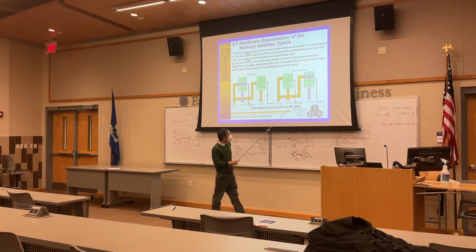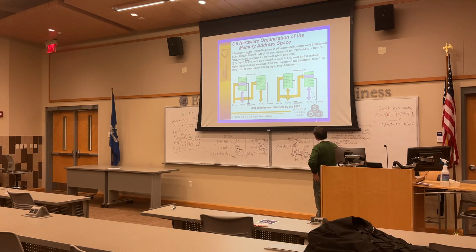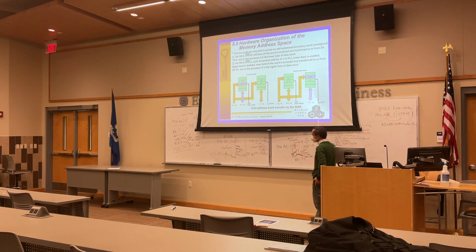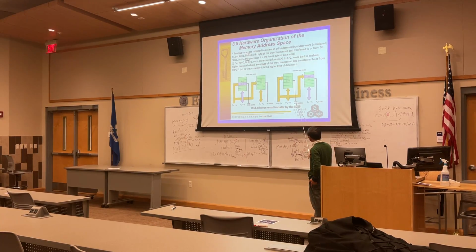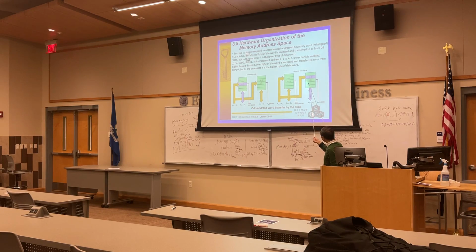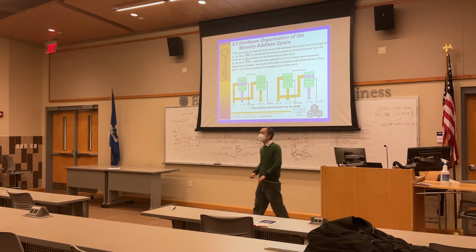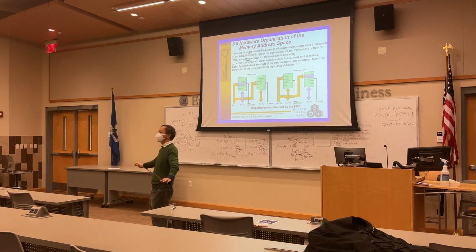After that, increment your address by 1, so that it becomes 1236H, an even address. A0 is 0, enable the lower bank, then set BHE to 1, disabling the high bank. Then we send the address, and the higher byte of the data actually stays in the lower byte of your memory, so we take it out on the lower byte of the data bus. But the microprocessor knows that this is the high byte data and sends it to AH. Done. Very complicated, right?